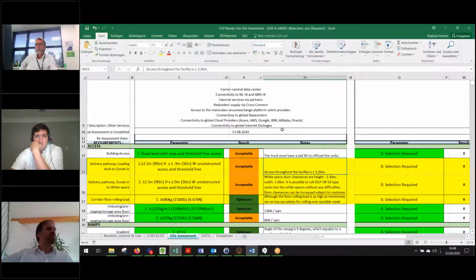Stefan, may I interrupt for a sec? Yes. Because we are a little bit under a time challenge in total, just to give a very brief answer to that question: we're definitely able, as we've proven already, to build racks up to 20 kilowatts. It's no issue to cool at all. Depending on the room, we either have to amend the cold aisle, and we have some low density rooms that we do not even take into the equation when it comes to OCP.